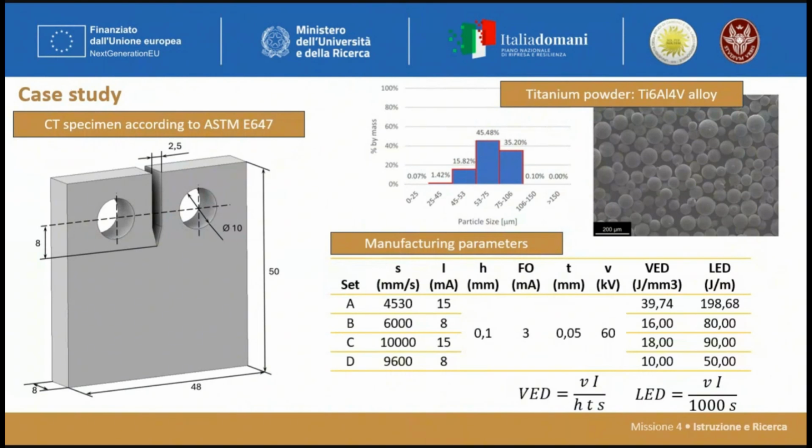As concerns the raw material, this is a powder bed process, and consequently we used powder. The metal considered was a titanium alloy, Ti6Al4V, with vanadium. That is an alloy commonly used for aerospace applications. Here we can see micrographs of the raw powder. We can observe the shape of the particles, which were almost perfectly spherical. The deformed particles were very few.